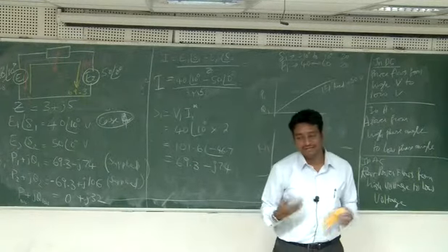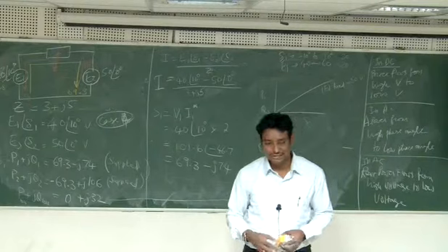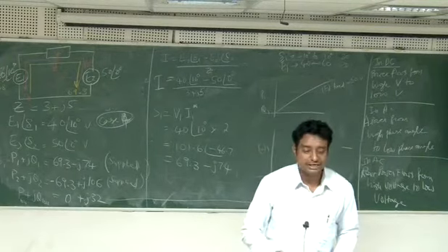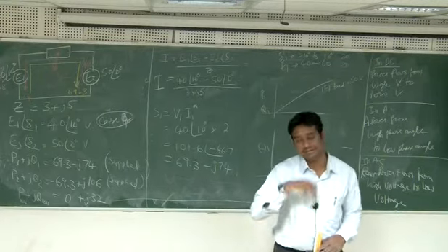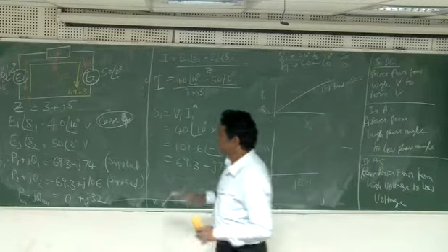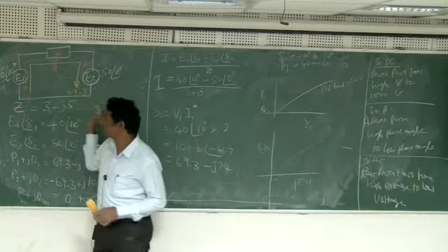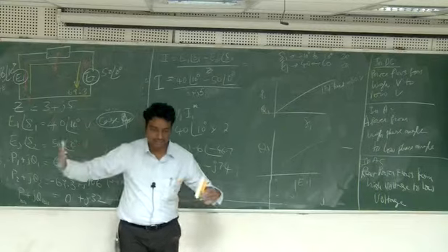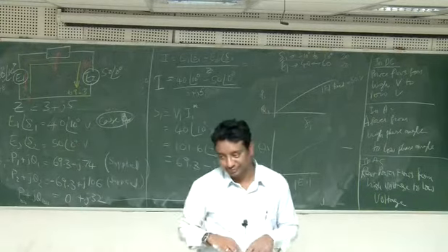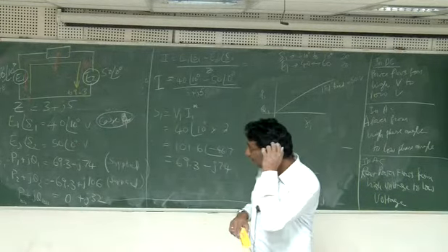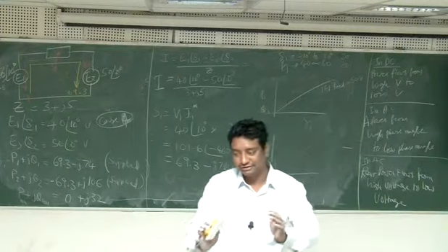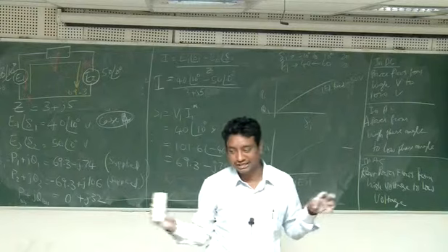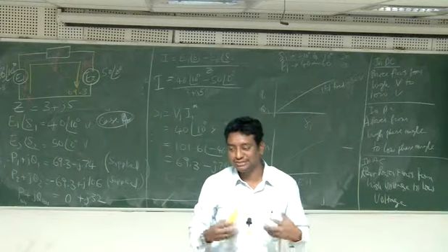Okay, so the question is why we are having three phase. Maybe next class on Monday we are going to talk about three phase. The reason for going to three phase is I want to transmit power from one place to another place. The distance may be 200 kilometers or 400 kilometers, long distance. I want to transfer the power. So the question is how to transfer more power with less weight or less volume of transmission lines.